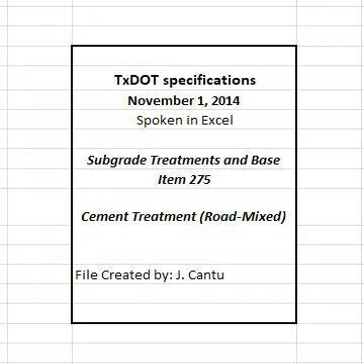4.3.2 Slurry placement. Mix the required quantity of cement with water, as approved. Provide slurry free of objectionable materials and with a uniform consistency that can be easily applied. Agitate the slurry continuously. Apply slurry within 2 hours of adding water and when the roadway is at a moisture content drier than optimum. Distribute slurry uniformly by making successive passes over a measured section of the roadway until the specified cement content is reached.